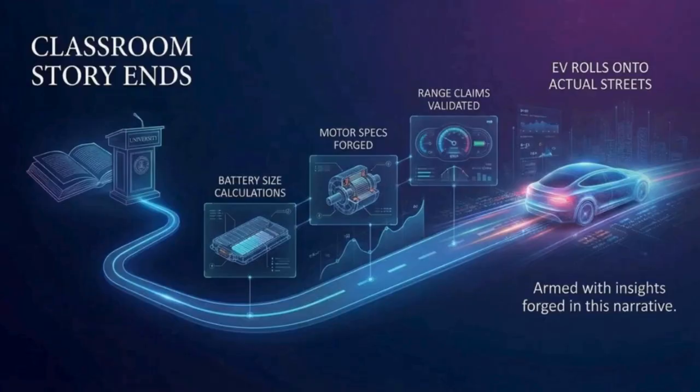Designing an EV without a driving cycle is risky. If we ignore the drive cycle, the vehicle may become overbuilt, with a battery that is too large and too heavy, or the motor may be too small, causing weak acceleration and power stalls. Without this, design becomes guesswork.